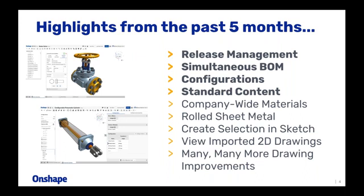So you're going to see a new tab for BOM table at your assembly level. You click that, and your bill of materials will fly out. It's a really neat way to interact with your assemblies, edit metadata associated with parts or subassemblies in your assembly. It's a very neat layer to Onshape. The bill of materials in Onshape isn't just a table in your drawing, it's an object at the assembly level that you can interact with.